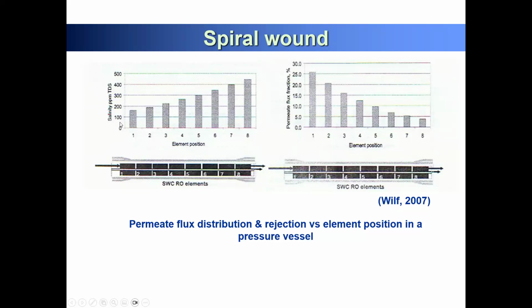So your permeate total dissolved solids is lower than the last element, because the last element has a high concentration of your salt. Then you pass through more salt. So you can see it is already more than 2 times higher in salt concentration, which means for your final product, you need to calculate, combining all the permeate water, how much concentration we need to design.